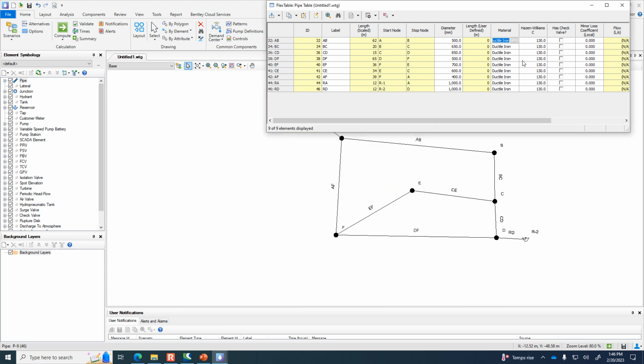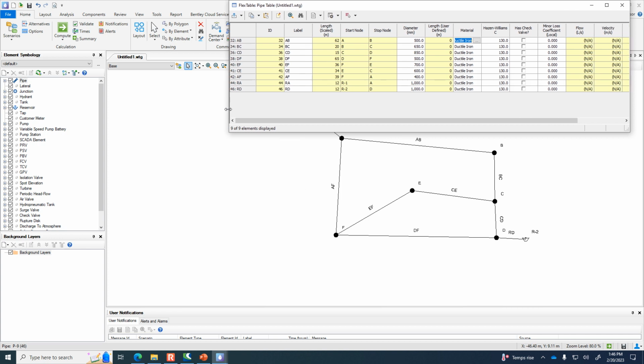You'll notice that it mentions the Hazen-Williams C. We can have the computer do its calculations in the Hazen-Williams method or the Darcy-Weisbach method. Does anybody remember which is more accurate? Darcy. Darcy-Weisbach's more accurate. So we don't care if it's hard for the computer to do its calculations. It's got plenty of horsepower to do that. So we're going to, in just a moment, go in and change it so that it, by default, uses the Darcy-Weisbach equation and gives us the maximum accuracy.